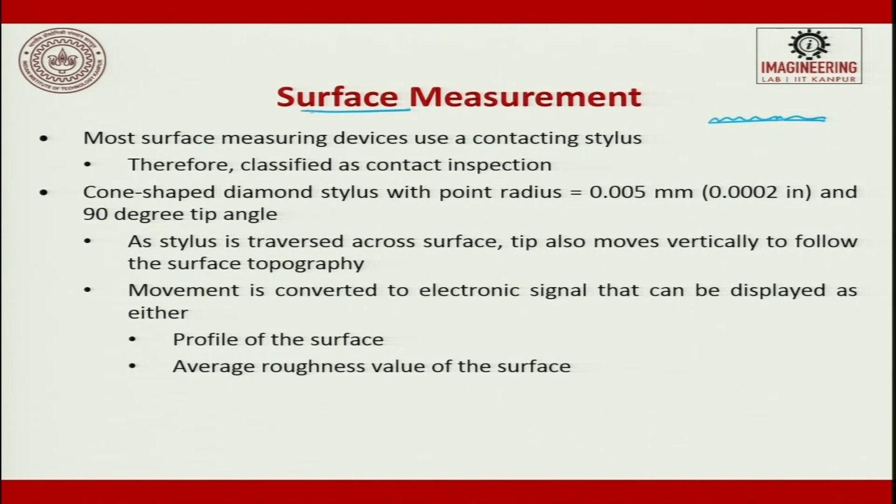These sharp edges can become stress concentration points during a fatigue cycle, and the component can fail. Or when you have a sharp edge, when water gets deposited, corrosion can start from there. So, it is always advisable to have a flat surface as compared to a rough surface for certain applications.